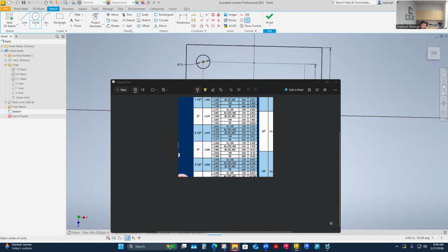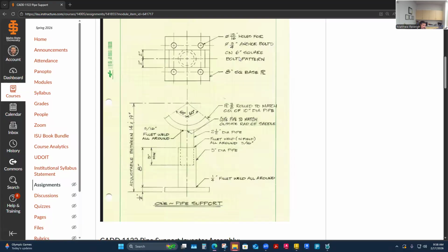I remembered off the top of my head that the hole is 13/16 for the bolts that are 3/4 inch. That makes a 1/32 difference. It's a 16th inch difference, but really a 1/32 of clearance all the way around. This is a pretty sloppy clearance, even only being a 1/32 all the way around.